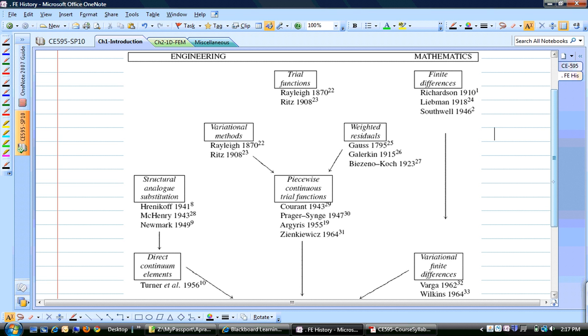And here is the heart of how we are going to approach finite elements. You can take your governing differential equation, which is nothing but an equation of equilibrium. Does anybody remember the equation of equilibrium from mechanics? Divergence of S plus b. Does that ring a bell? Okay. And we'll talk about that next time also. That is a differential equation that we are trying to enforce.